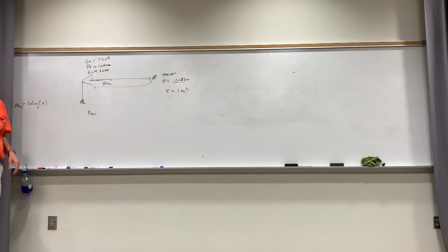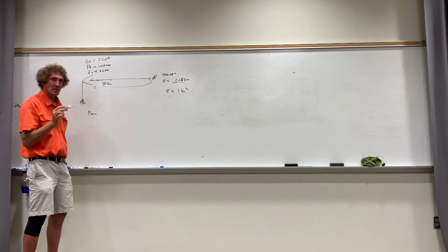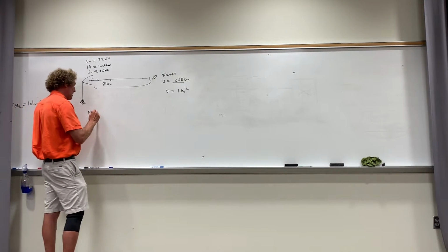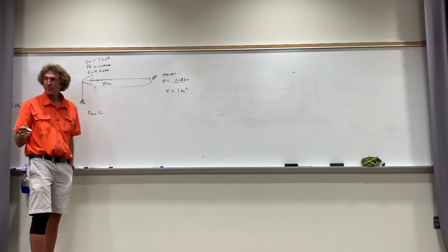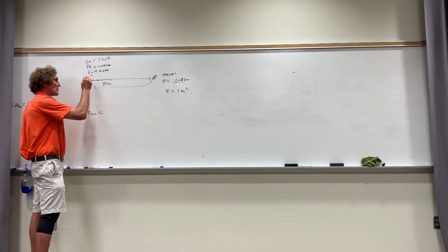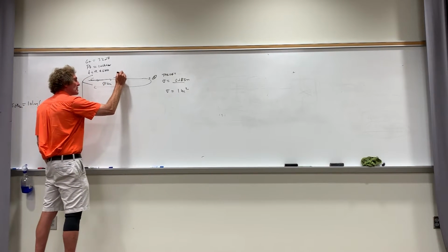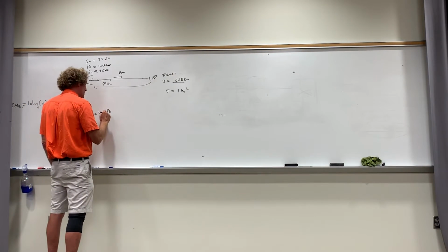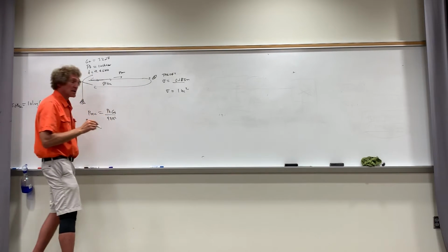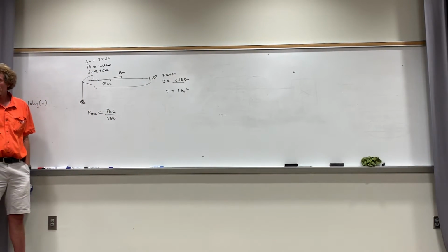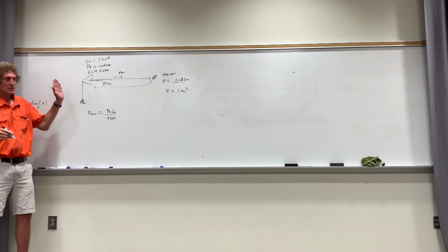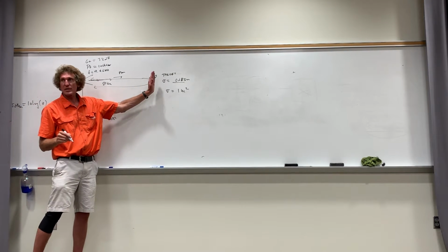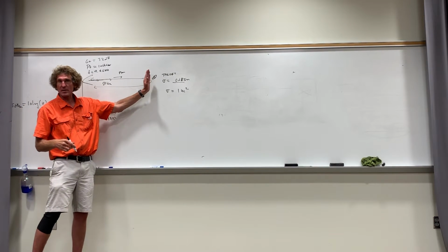So if we wanted that power received back at the antenna, not the power density, but the power, here's how I would start if you don't remember the formula. Start right here and find the actual PAV, right? The average power density, and that would be what? The transmitted power over 4 pi r squared times the gain of the transmitter, the linear gain of the transmitter, correct? Now, once that's going, it comes on and it strikes this and is re-radiated in all directions isotropically, right?